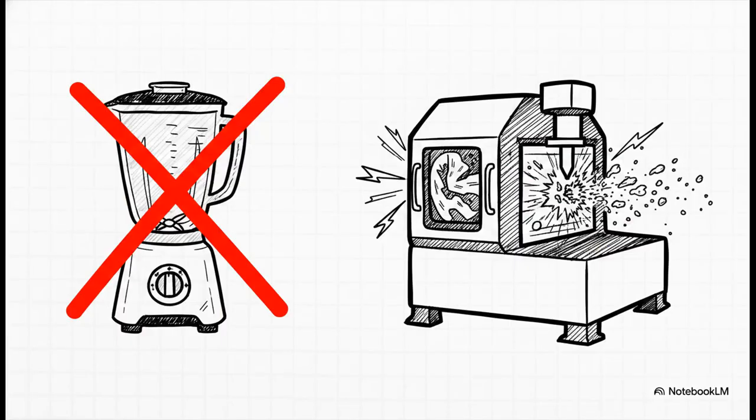And taking this from a lab scale to an industrial scale requires some truly incredible physical engineering. You can't just use a standard kitchen blender to make industrial quantities of mayonnaise. Food scientists use intense equipment like colloid mills, which shear liquids between a rapidly spinning rotor and a stator, with tolerances of literally 1/1000th of an inch. Or they use homogenizers, which force these liquids through tiny orifices under massive pressure, utilizing extreme turbulence and literal ultrasonic cavitation to smash droplets down to sub-micron sizes.